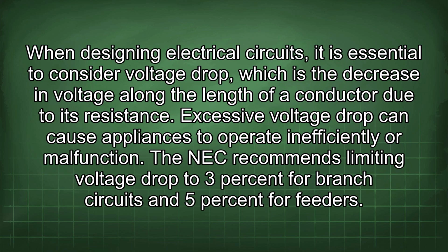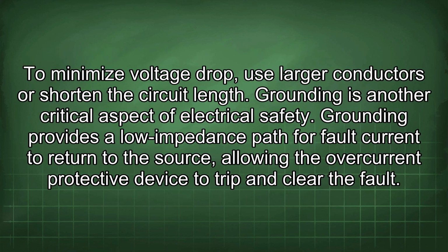When designing electrical circuits, it is essential to consider voltage drop, which is the decrease in voltage along the length of a conductor due to its resistance. Excessive voltage drop can cause appliances to operate inefficiently or malfunction. The NEC recommends limiting voltage drop to 3% for branch circuits and 5% for feeders. To minimize voltage drop, use larger conductors or shorten the circuit length.